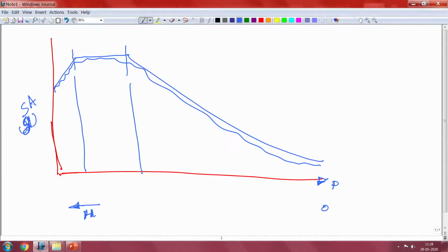So like this. We have discussed that this is the spectral acceleration or PGA. When the structural period is 0, your input motion will have the same signal, so the maximum input motion is the PGA. Okay. So this is basically a response spectrum. This can also be plotted in the tripartite plot. So this is for one ground motion.